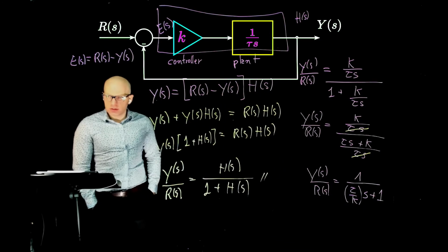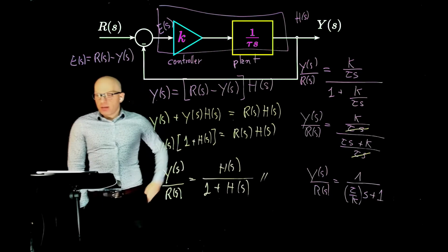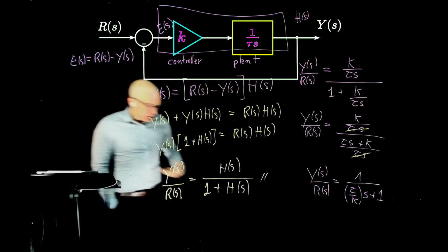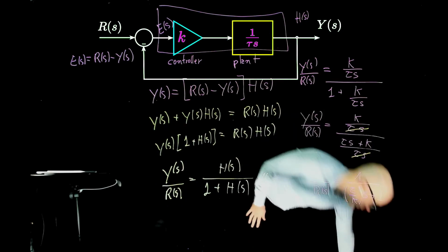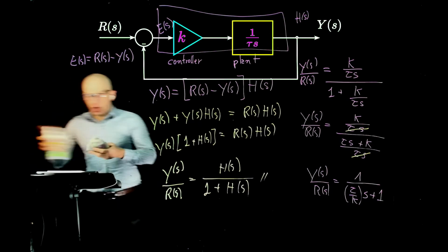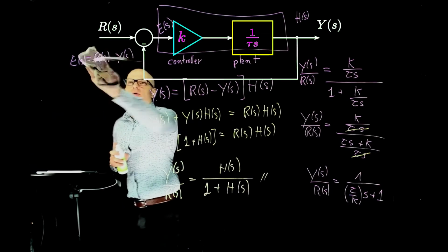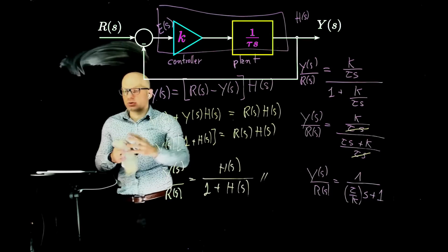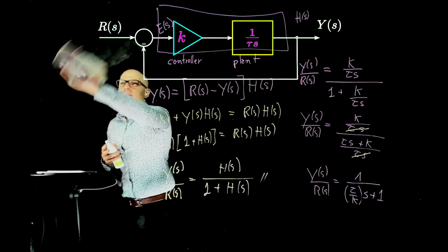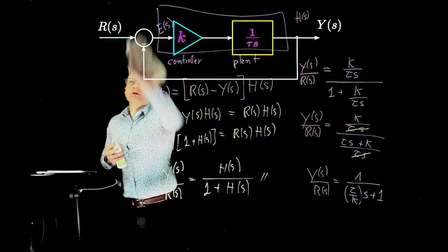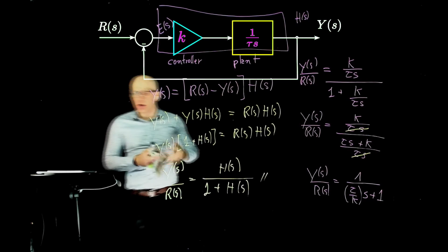Okay, what is the time response for this? Because it is a first order system, we are dealing with an exponential component in the output. And this exponential component can now be controlled based on the value of k that we can choose. This proportionality constant, in the example I gave, would give us the aperture of a valve based on the error in the system.